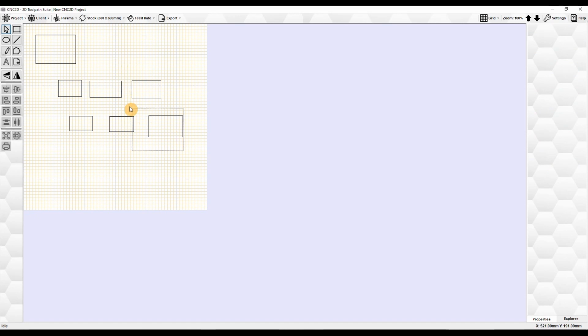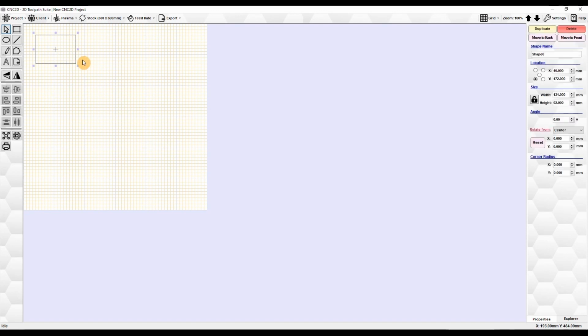Now what we can do is we can obviously select these. We can choose to drag shapes around and move them wherever we'd like. You can hit the delete key on your keyboard and that will clear those shapes there. And so then basically what you have here is you can have a whole bunch of different ones. We'll put down an ellipse. Let's put down a line. This is a polyline, which basically, if you just left click and start to drag, you see it'll position all of these points on here to make just a regular line.